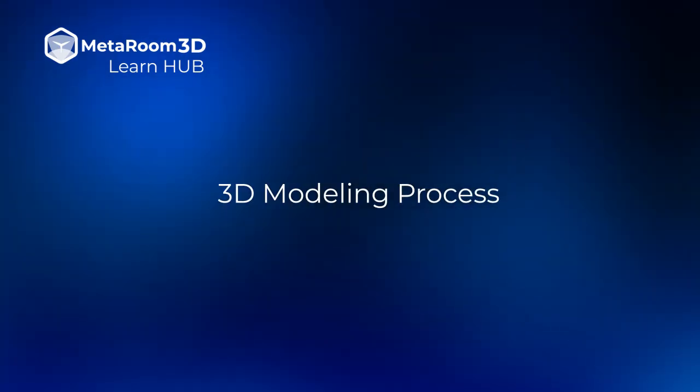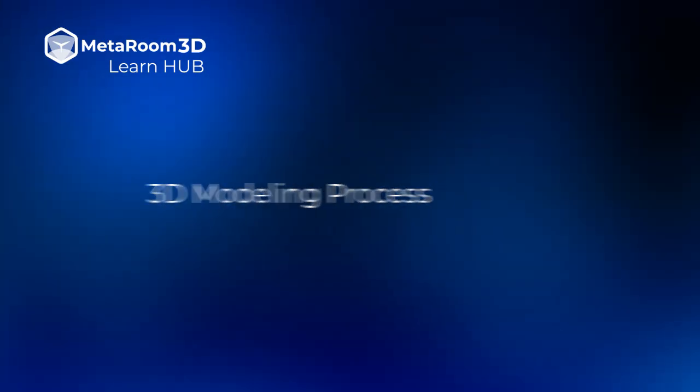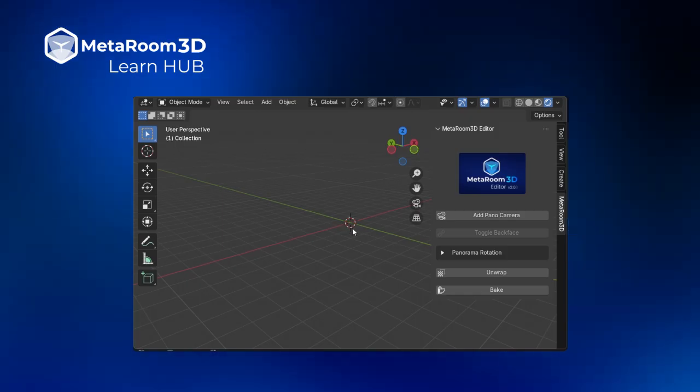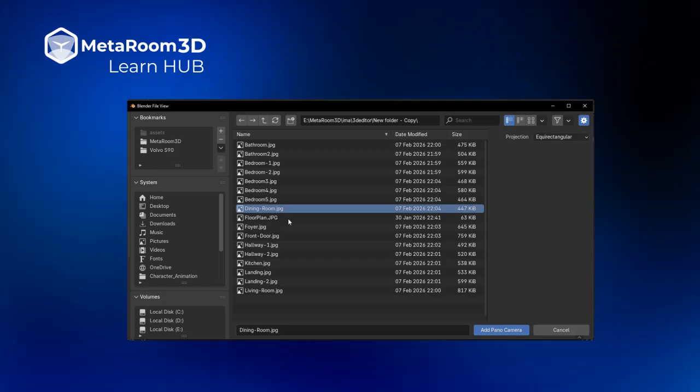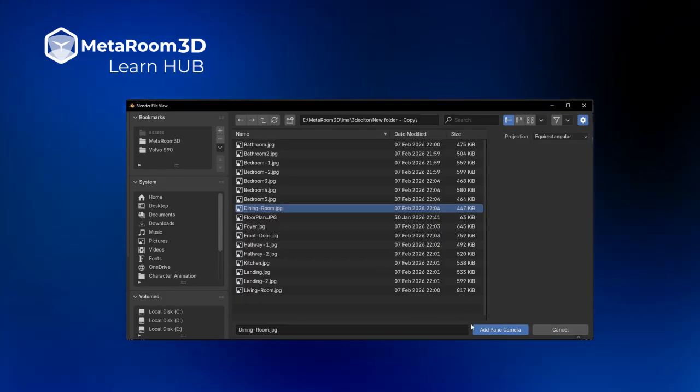Now let's begin the 3D modeling process by importing the first panorama. Click on Add Pano Cam, then select your panorama image. After selecting the image, click on Add Pano Camera to load it into the scene.